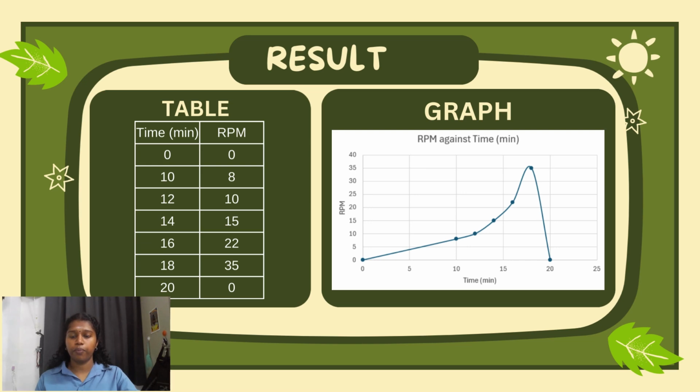Second, insulation properties. The soda can acts as a basic insulator, preventing rapid heat transfer to the water. Lack of insulation around the can allows heat losses to the surrounding air. Adding an insulating material like styrofoam around the can could minimize these losses.